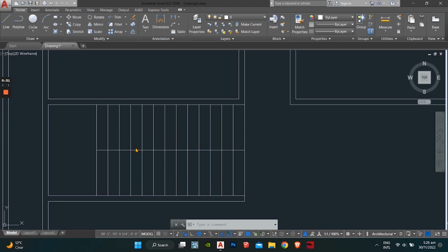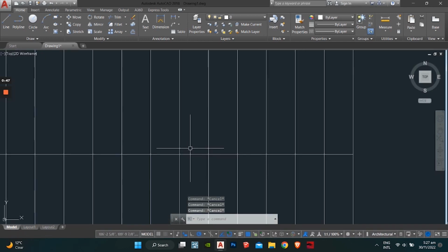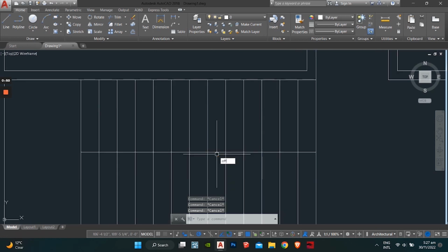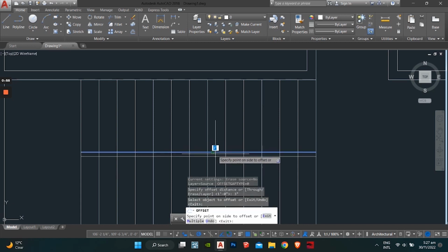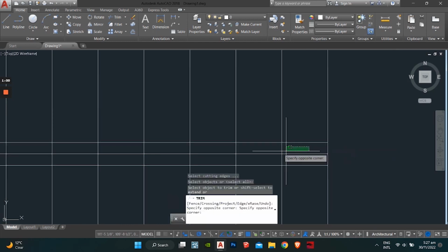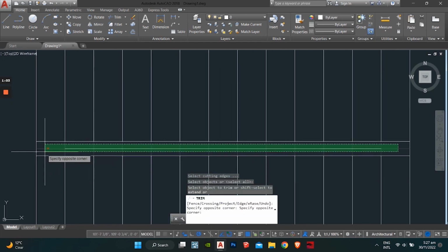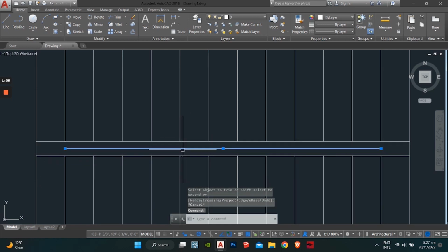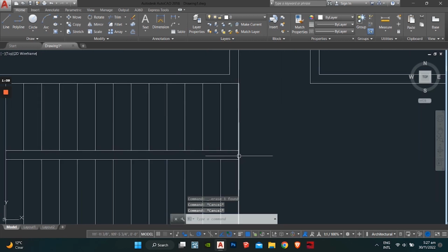And usually the houses are around 10, 11 feet high. And if we include the slab, that's going to be around another foot. So this is fine. 12 feet is fine. Okay, so how do we treat the stairs? What we're going to do here is we are going to offset 3 inches here and 3 inches this side and 3 inches this side, and we are going to remove all of these lines. Okay, delete this one.